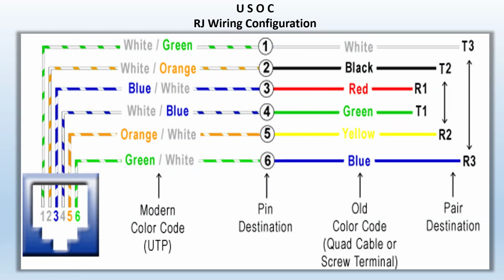So the Cat5e cable, for example, or Cat6, if you really want to spare the money, or if that's the only thing you have, yes, Cat6 also can be used as a telephone line to extend it from the demarcation point, which is the point of entry where the lines are coming in, to a desktop or something like that. Yes, it can be used, but the telephone line cannot be used as a data line wire because it just doesn't have the ability to carry the data signal. It has to do with the arrangements of the pairs and the twist that the pairs possess, mostly.